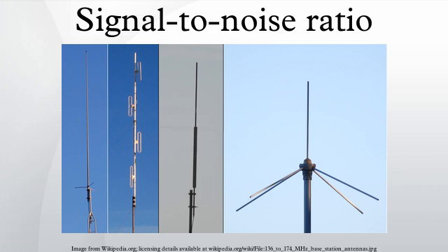But in signal processing and communication, one usually assumes that the resistance factor is not included while measuring power or energy of a signal. This may cause some confusion among readers, but the resistance factor is not significant for typical operations performed in signal processing, or for computing power ratios. For most cases, the power of a signal would be considered to be simply where A is the amplitude of the AC signal.